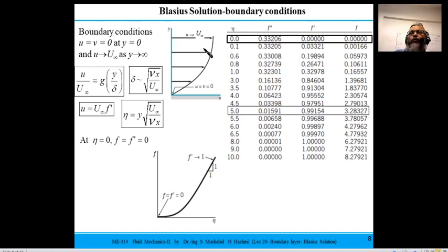And we know once y reaches the boundary layer thickness, then u would approach u infinity. So your first derivative would end up at unity. So this is what you see here, when eta increases in such a manner that your first derivative approaches 1, then we can say that your local velocity would approach the free stream velocity.